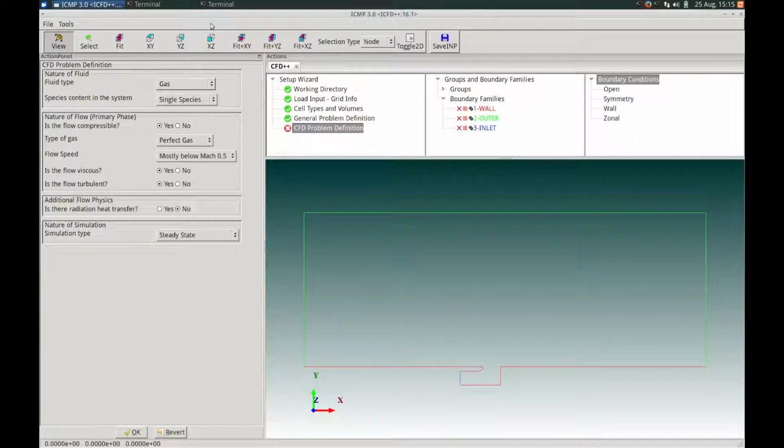The purpose of this example is to show how the stator blade source term model along with the porosity model can be used to represent the turning mechanism inside a thrust reverser bucket without modeling the actual stator geometry. The source terms are enabled in a specific region of the mesh, and they introduce pressure loss and area blockage effects that are analogous to the presence of a row of stator blades. These source terms will be enabled in the region where my mouse is currently hovering.